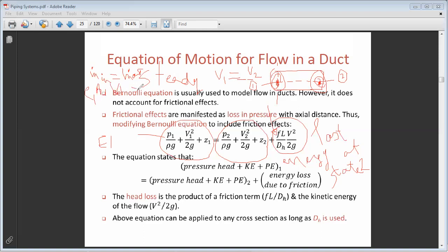Of course here, even if the velocity is not constant over the cross section, it's a parabolic profile. Now we will demonstrate it together. So when we calculate m dot, we cannot just say it's rho A V. We should perform integration. Now we'll do it together. So it's like a V average, okay? But because V average is constant and the profile is not changing, the maximum here is equal to the maximum there. Now we will derive it together.